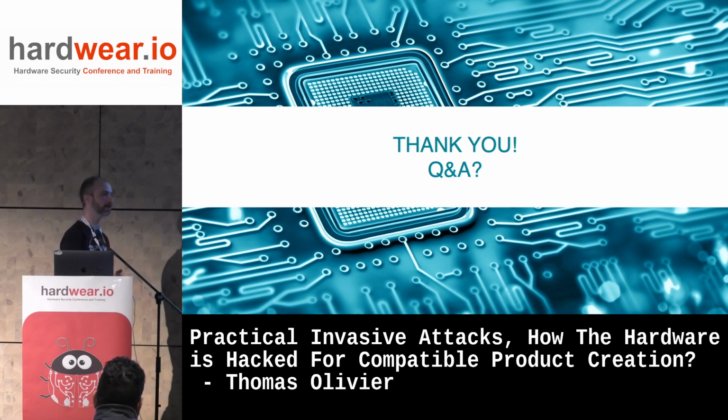So it would be great to simulate the entire chip. First, I think it's slow and complicated on any computer, and second, I think it's not possible to get a 100% accurate netlist of the digital circuit because it's big, and you'd have to spend the time to clean it all, right? So that's why I'm isolating parts of the circuitry. Fetching, right? That's one thing. Instruction decoder can be another one. So you want to stay small.